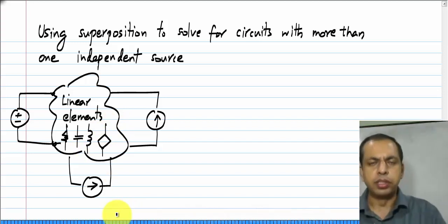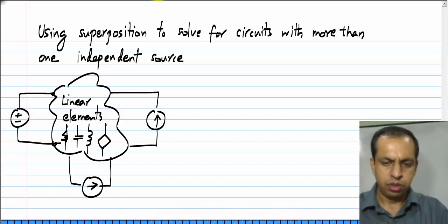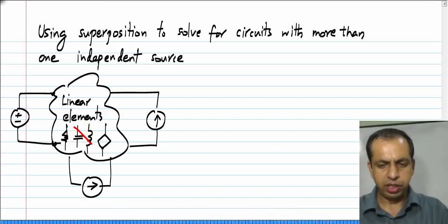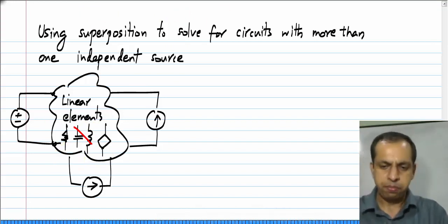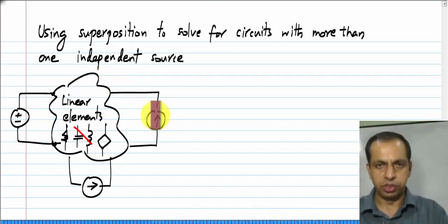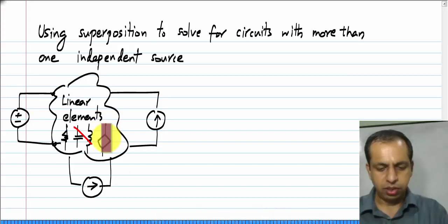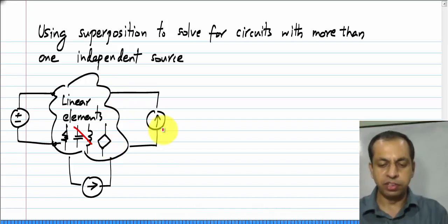Now, in the initial part of the course, we will be looking at circuits without inductors and capacitors, that is circuits without energy storage elements. So, even these will not be there. So, essentially we will be discussing circuits with resistors and control sources. Okay. So, everything is enclosed in this except for independent sources, and of course, the condition is also that for these linear control sources, the controlling quantity is within the circuit.